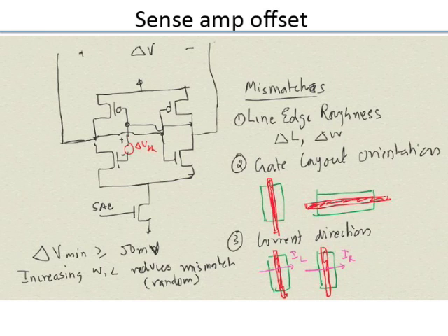If you recall the memory cell flat layout, all the transistors are in the same horizontal orientation. Here in addition, you could try to make the current directions the same, but it turns out the layout becomes messier. If you were doing very sensitive analog circuits, you could try that, and there are certain other things you could do to improve the matching.